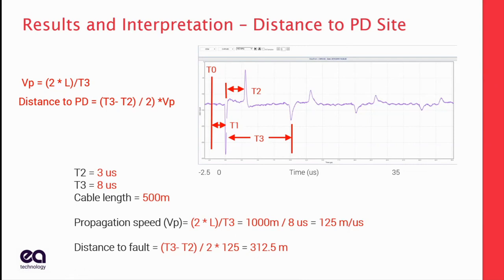And if I look at my cable diagram, I may find the splice or I may find the termination. The idea of online testing is not to detect this all the time. It's to let you go through 20, 30, 40, 50 cables in a day, rule out 90% of them, like the Electricity Northwest example, and address those 10%. At some point, I'm going to have to take action.